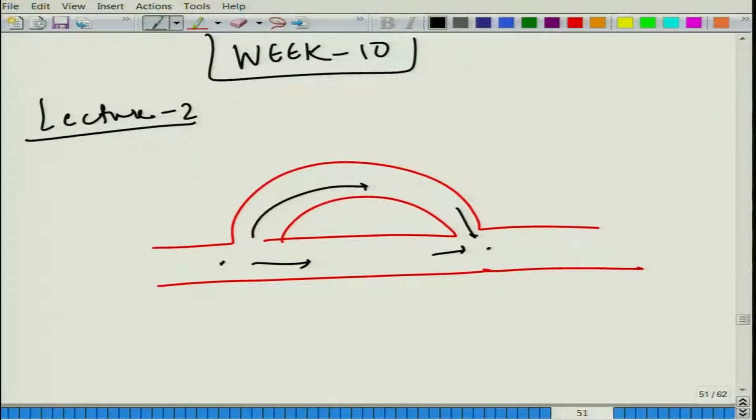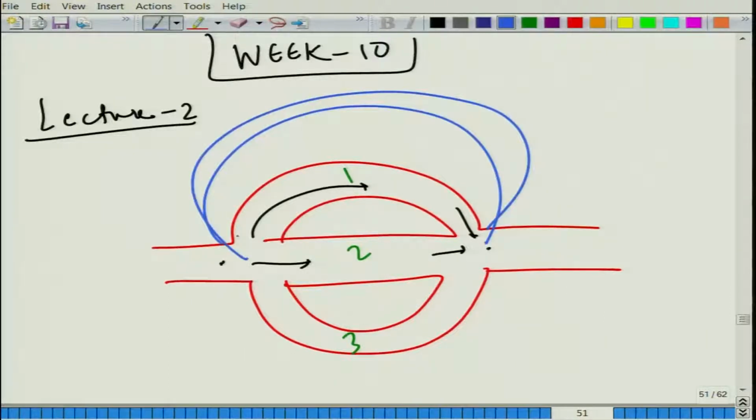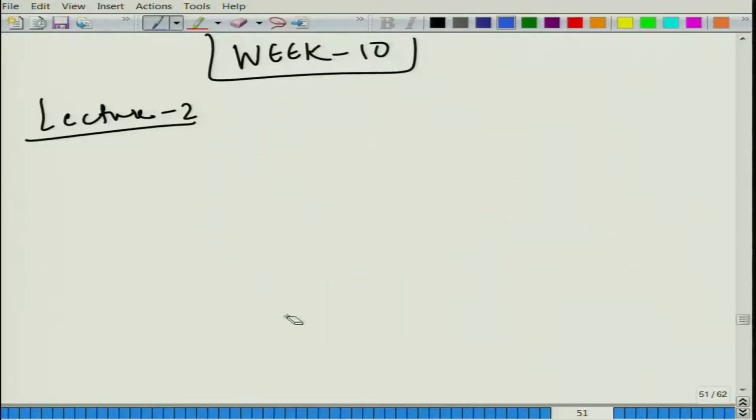Then there are a bunch of papers which talk about the modified Herschel-Quincke tube, in which you have even more tubes attached. For example, things like this one. So, they are basically like 1, 2 and 3 pipes, or they could be more. There could be n number of such pipes, each with different lengths, and the constructive or destructive interference causes resonances.